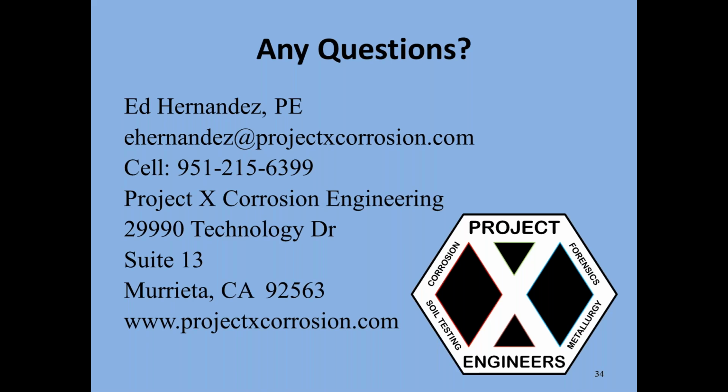And then this next one is asking about the amount of soil sample necessary for a full suite of corrosion tests. What would you recommend? Yeah, you only need 300 grams of soil sample. So a soda can, basically, it fits in a sandwich bag. That's all you need. It's easy to mail. So just a plug. But yeah, that's all you need to be able to do the soil box test and create the extract for the Caltrans extracts and to test for the various water soluble salts.